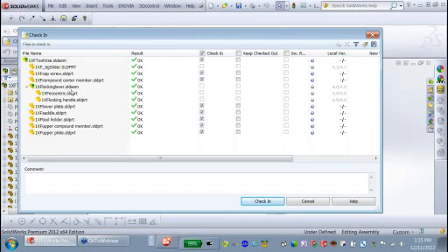As we know, this lower locking lever mechanism was already checked in as a sub-assembly, doing a bottom-up check-in. Someone else may have checked it in while I was working on the upper assembly. Whatever the case may be, it's already captured in the core system. So I'm only going to transact those parts that I choose to check in at this point. I could uncheck or check in certain subcomponents that maybe I don't want to capture, and I have that flexibility. I'm going to go ahead and let the system check in all the structure though.